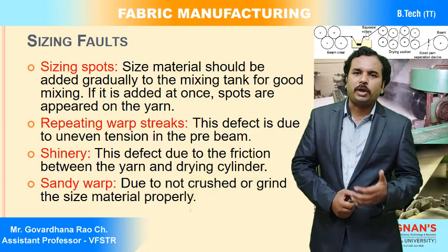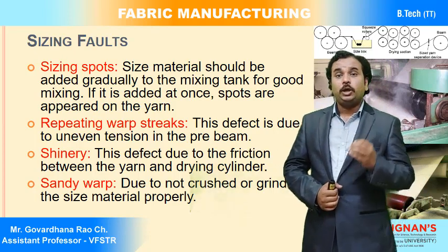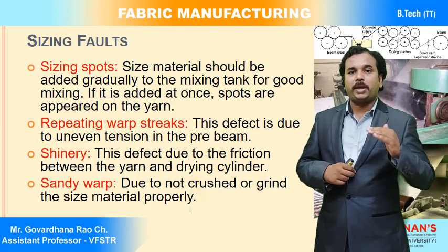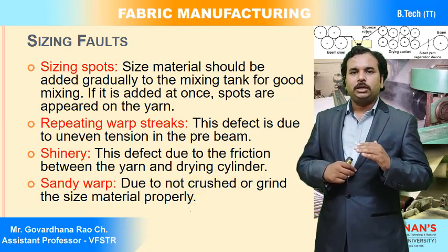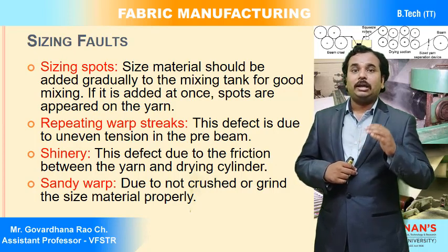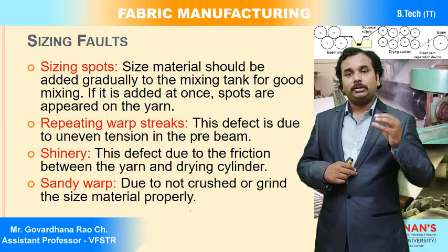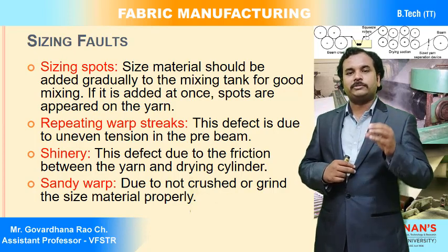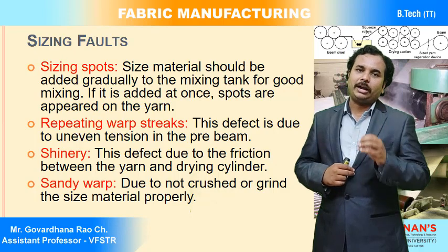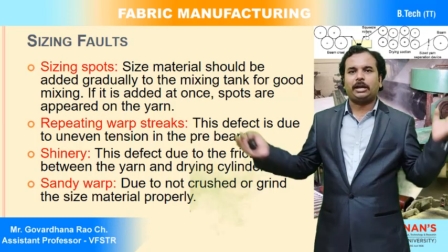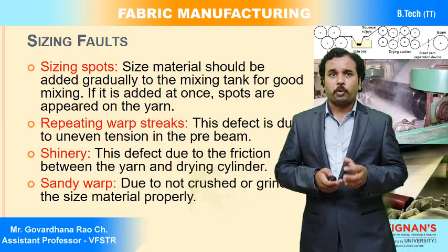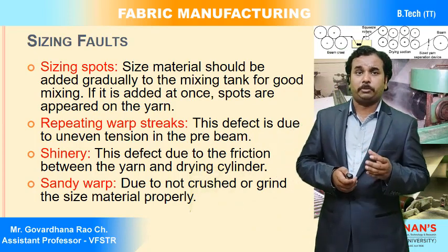So the viscosity is going to become thicker, more viscous. That is why we need to check the size paste level in the size box every time, and add a small amount of size paste into the size box gradually. If you add everything at a time, then obviously you will get size spots in the sized warp sheet.